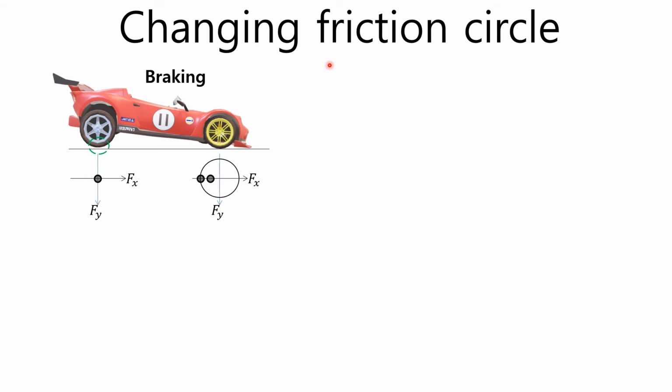The size of the friction circle and the location of the driving state depend on the driving condition. When the rear wheel reaches the tilting braking, the rear wheels come off the ground and the rear wheel friction circle becomes the friction point. On the other hand, all the weight is shifted to the front wheels, which increases the friction circle on the front wheels and increases braking friction force.